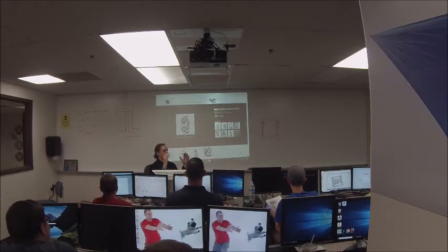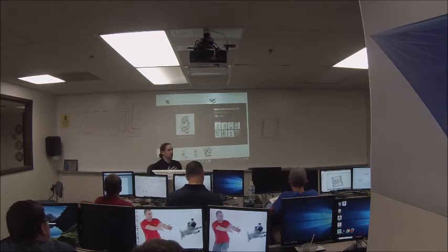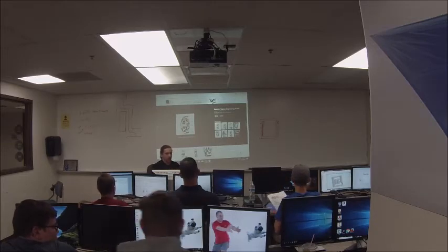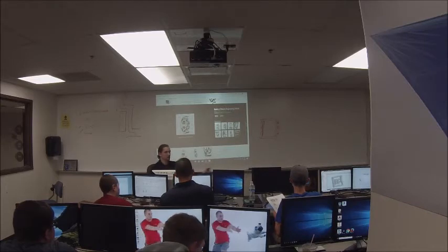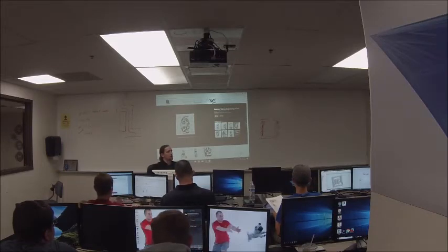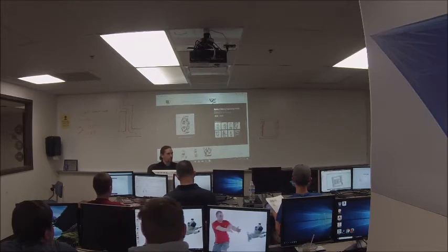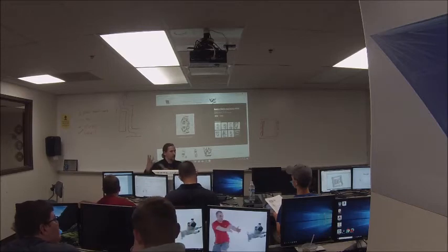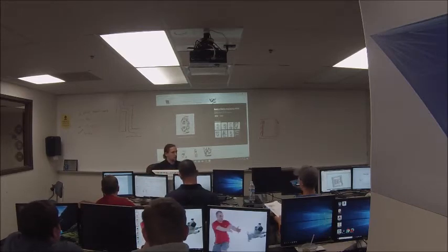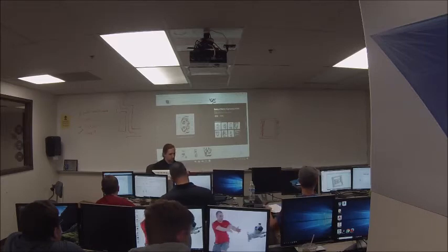The round groove keeps the ball in. So if you think about pushing on the bearing in the forward direction, the thing doesn't just come flying apart, right? There's some engagement there, so that the bearing holds together, and it can handle load in this direction, and that's what's called the thrust direction. You're pushing against the bearing. The radial direction is the direction the bearing's normally supposed to support, like side load on the shaft, but the thrust direction is pushing against it. Radial ball bearings don't fail under thrust load. Now there are bearings meant for handling thrust load, but you're not going to pop your bearing apart if you put any load on that. Right?